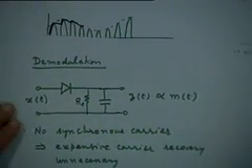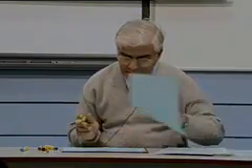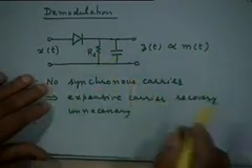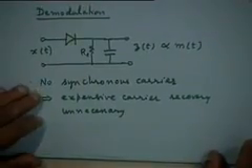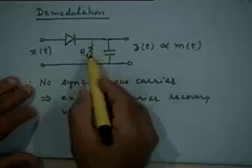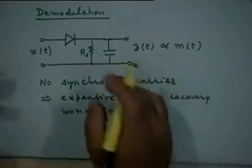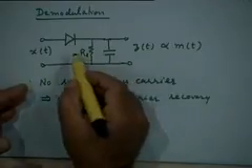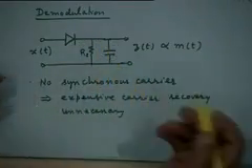Is that clear? Okay. So what is the RL? RL is this load resistance that I have talked about. Then why are you saying that RL is far greater than RS plus RF? I just explained, because if you assume that, then this would not come into the picture of the charging time constant. This will be so high that the charging current will hardly flow through this resistance. Most of the current will be used to charge up the capacitor, right? And therefore we don't have to worry about the value of R sub L in calculating the charging time constant.